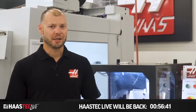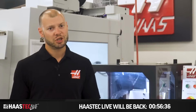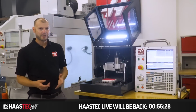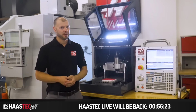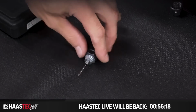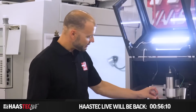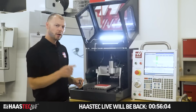I want to show you how easy it is to set up the desktop mill and use VPS conversational programming to generate some code. So you can see here, I have a couple blocks of plastic on the table to work with. We mostly recommend cutting plastic or machinable wax on this machine since the material is cheap and reduces damage if a crash occurs. Or, for the ultimate in simplicity, we offer the spring-loaded pen attachment which mounts directly in the spindle. Then you can put a clipboard and a piece of paper on the table and use the desktop mill to draw shapes with CNC code. But today, we're going to make some chips.